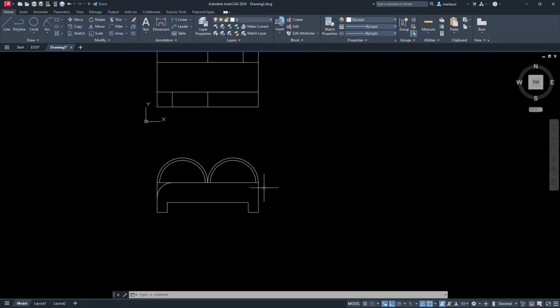All right, next thing I need to do is come over to this side and create the right side view. I can either use miter lines, or in this case it's a simple enough drawing where I don't have to do that. I can simply create it from what it is. So I'll go to the line command. I'm just going to touch this endpoint, and I'll drag over this way, and remember that I'm trying to keep these views in line with each other, right?